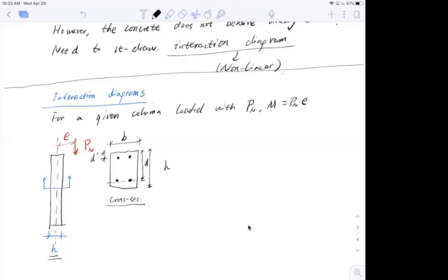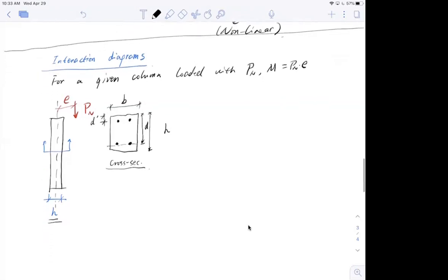So we know bending very well, right? So we can see the stress distribution, but be careful now. This stress is combined stress. So also look at the strain. The strain is also combined. So the strain distribution will look something like this. You see more compressive zone, c.